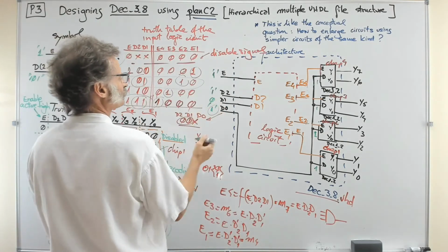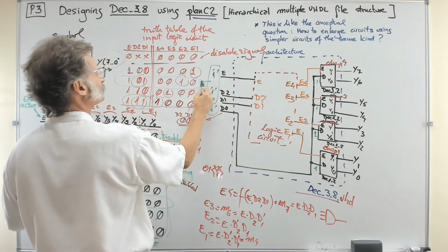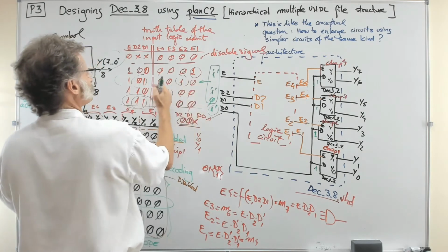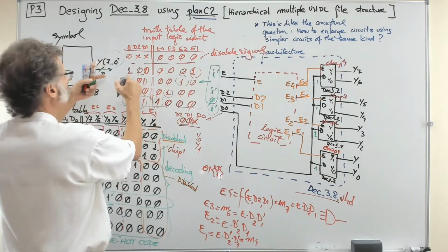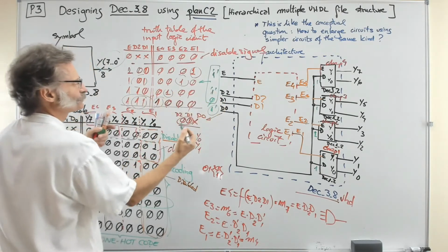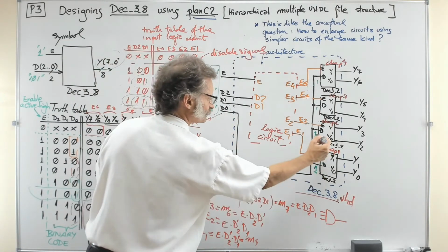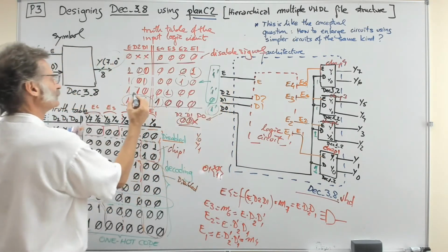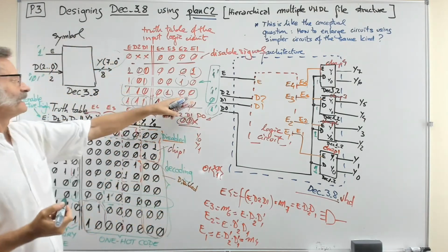What you are doing here is applying 1, 1, 0 to this table, not what I said before. I was thinking wrongly that the row in this case is 1, 0, 1, but that is not true, because this 1 in the D0 goes straight to the circuit, as I said before. So this is 1, 1, 0. So it is this row that is the one that is driven. So very well.